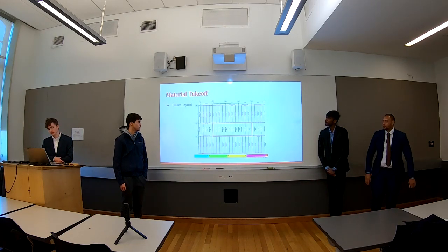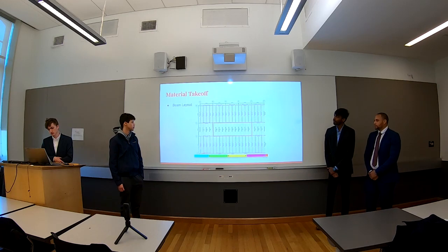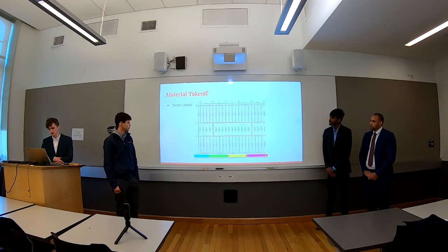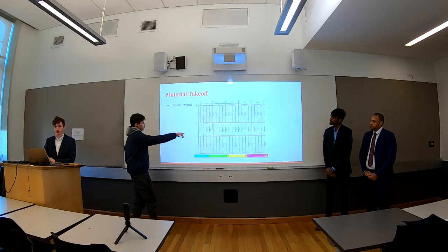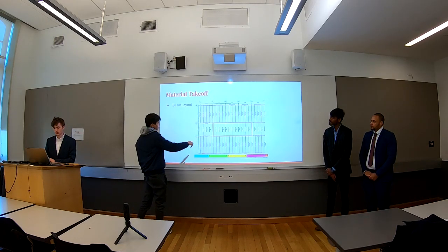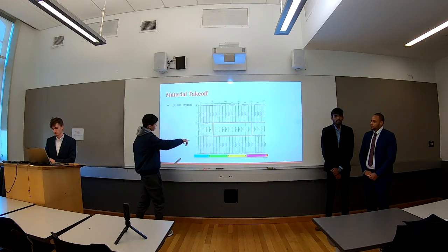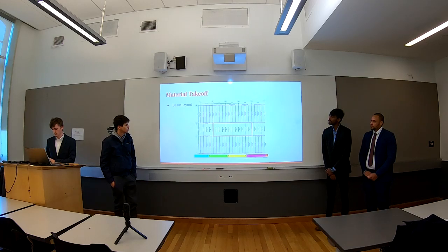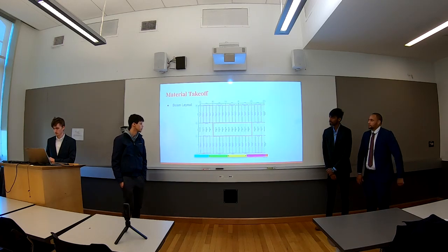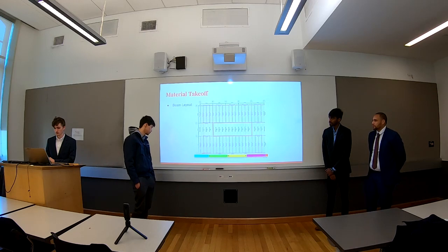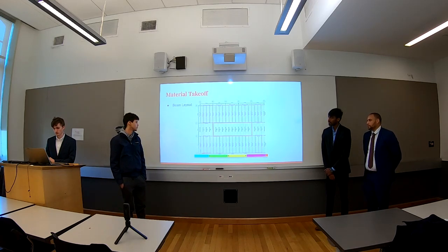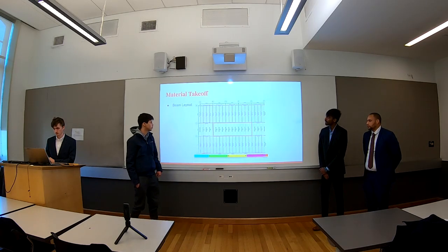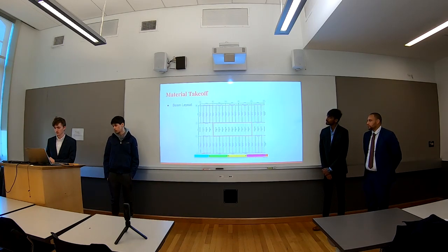Okay, so this is our beam layout. Our beams vary between W24 beams and W14 beams. The W24 beams are right here. They take up most of the loads, which is why they're the biggest. And the ones on the edges, like the W14 and W16, don't take up as much load, so they can be smaller. As you can see, the majority of the structure is composed of W18 by 35 beams, which are the purple ones on the sides. And the total count of all the beams, we're going to see in the next slide.